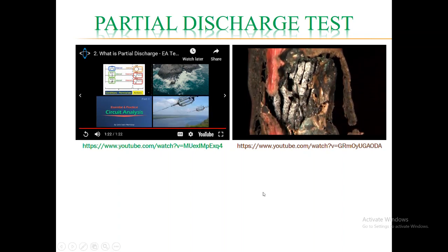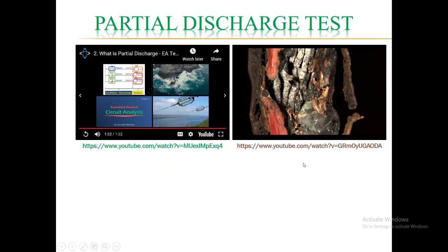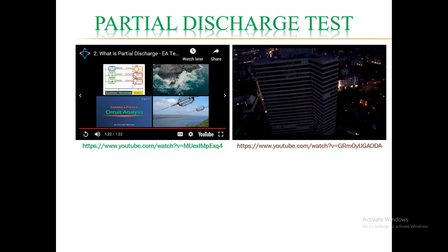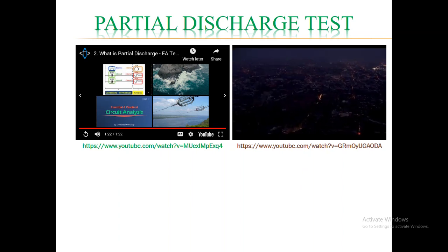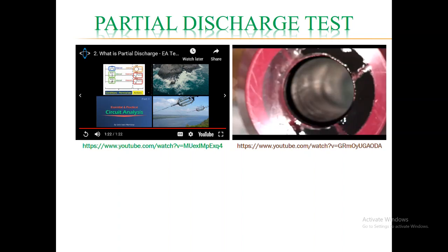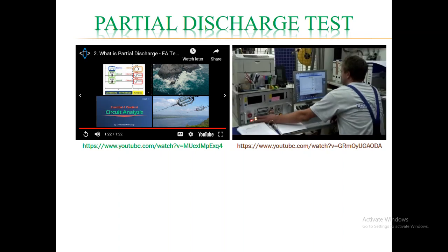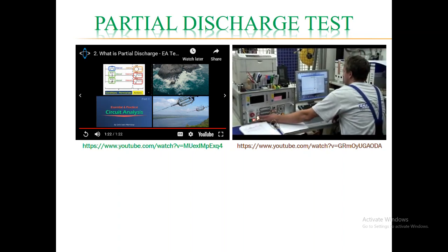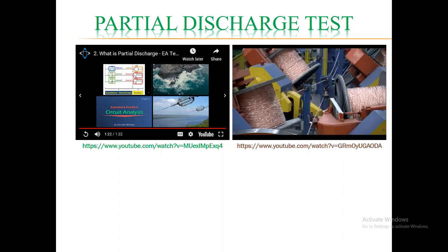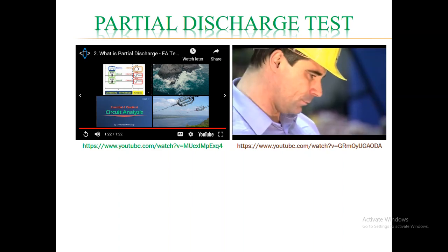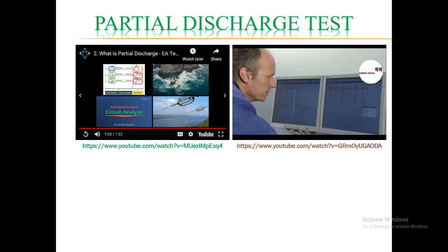Insulation breakdown can lead to dangerous situations, severe damage, and ultimately huge economic losses. The affected component needs to be closely analyzed to make sure the PD will not lead to further damage or even complete destruction. Therefore, the integrity of the insulation of high-voltage equipment should be confirmed using PD analysis during its manufacturing, its commissioning, and during its lifetime, so that it stays in good condition and is safe to operate.